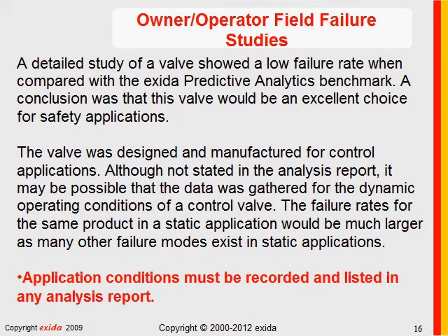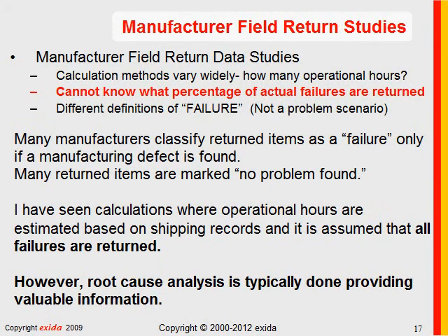The failure modes will be much different. There'll be cold welding. There'll be stiction. There'll be all kinds of modes in static applications that didn't even exist in a dynamic application. So, lesson learned, application conditions, including static versus dynamic, must be recorded and listed in any analysis report.